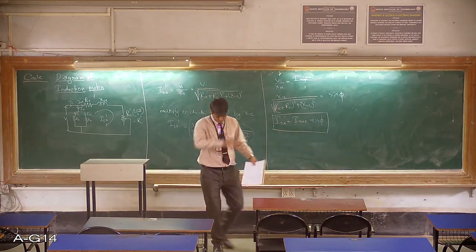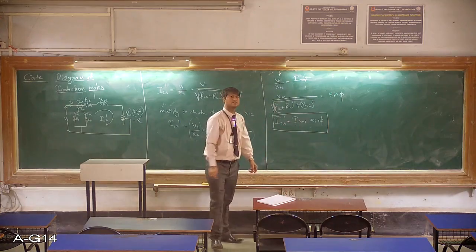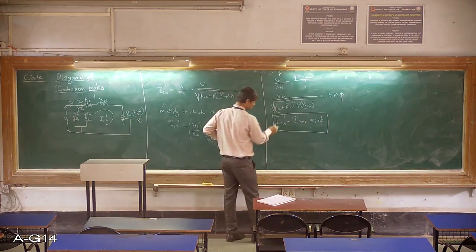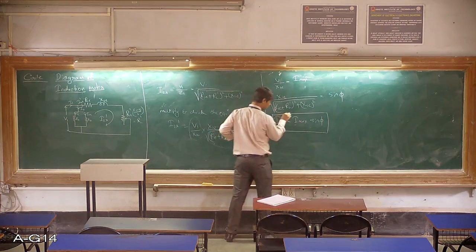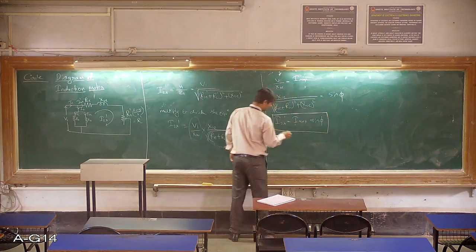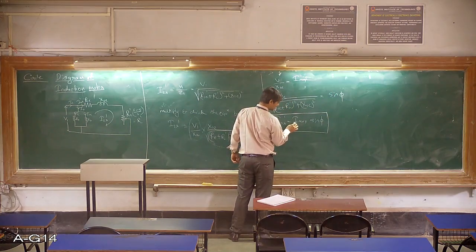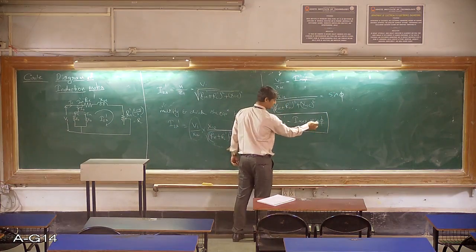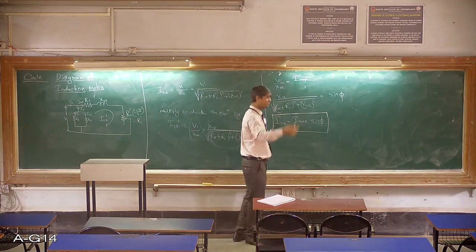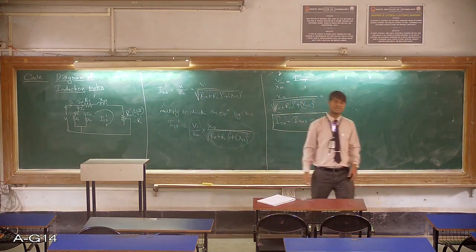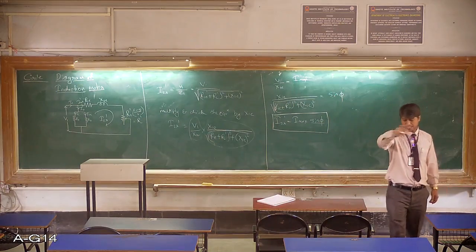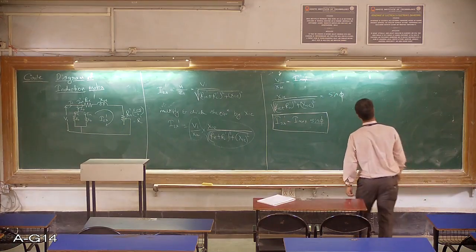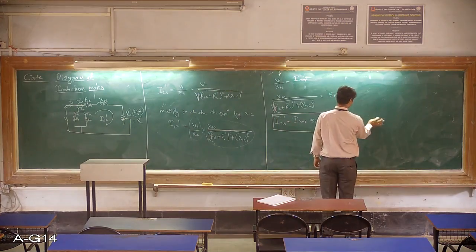Now I'll tell you why this locus diagram is actually called a circle diagram, because the equation for I2R dash has the trigonometric function sine phi, I max into sine phi. Since it is associated with sine phi, obviously the locus diagram for the induction motor will be circular in nature, so it is called a circle diagram. And here I'll show you how it actually looks like.